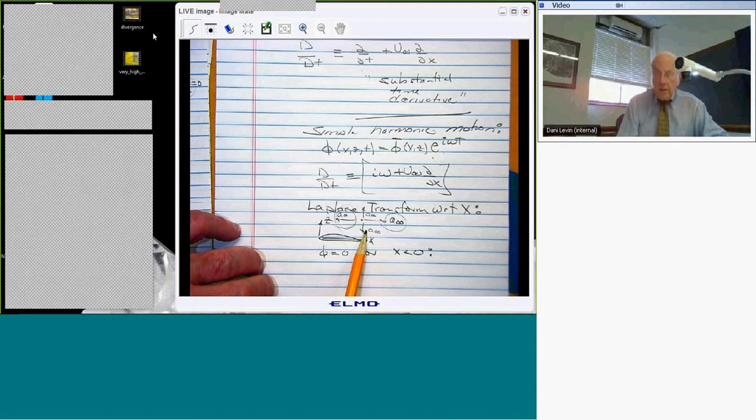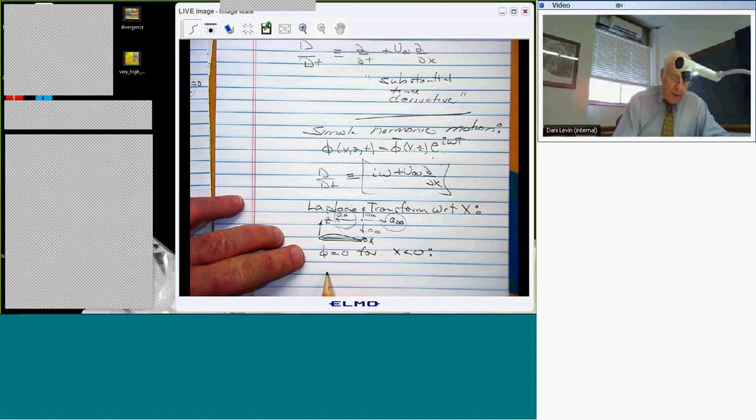So when this thing moves through the air and creates a disturbance in the flow, it propagates forward with the speed A infinity. But in supersonic flow, U infinity is greater than A infinity, so the airfoil is moving faster than the disturbance in the fluid. Okay, so it's only after the airfoil passes that you know it's been there. So more particularly, the propagation forward is this.